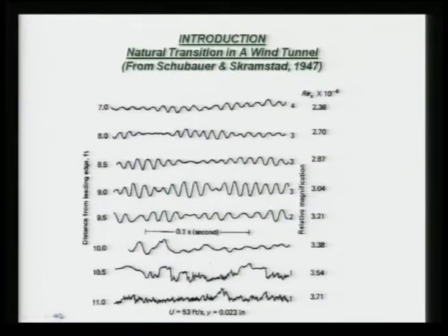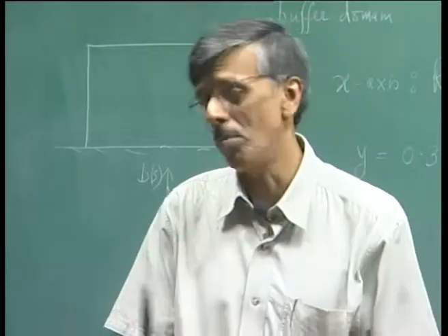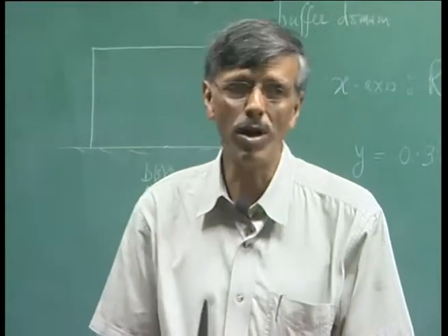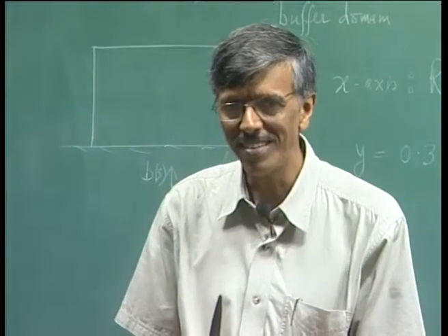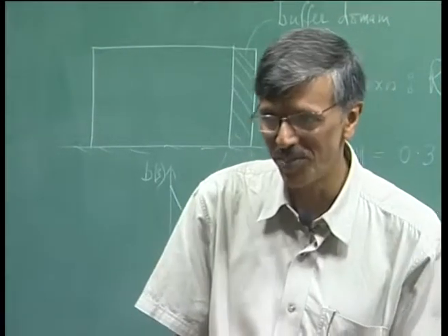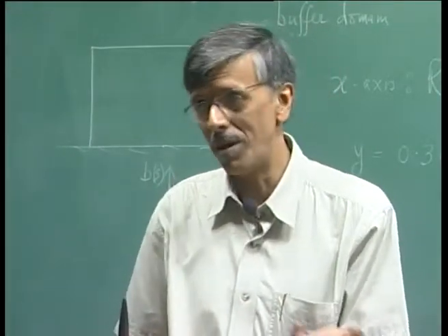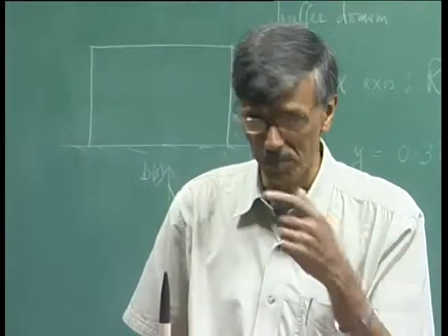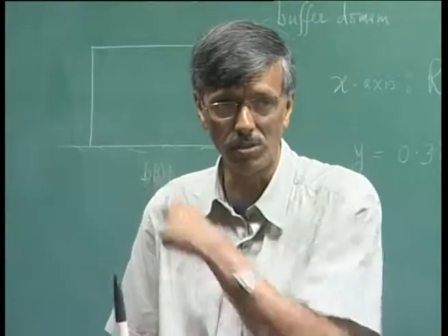But what happens is, primary instability is just one of the things. Primary instability is just the beginning of the story. So, now what do you have? You have the basic equilibrium flow plus a disturbance. Now, what should one do naturally? One should naturally also study the stability of this unsteady flow. See, your basic flow could have been perfectly steady, but because of the primary instability, now I have the basic steady flow plus an unsteadiness due to this primary instability.